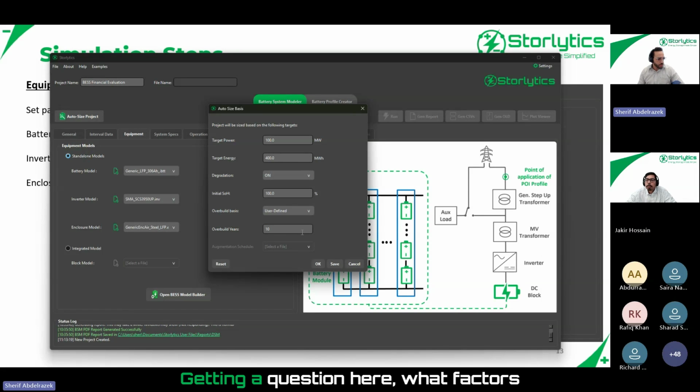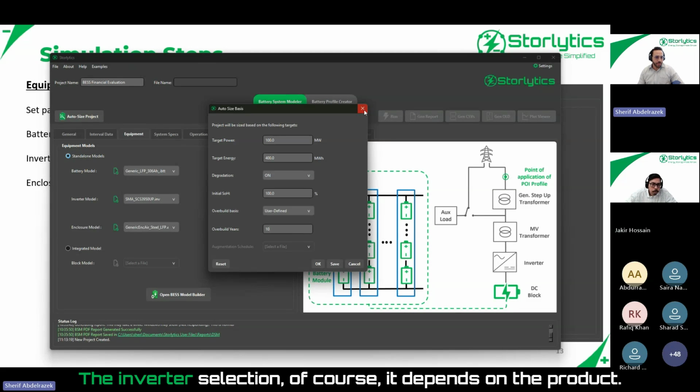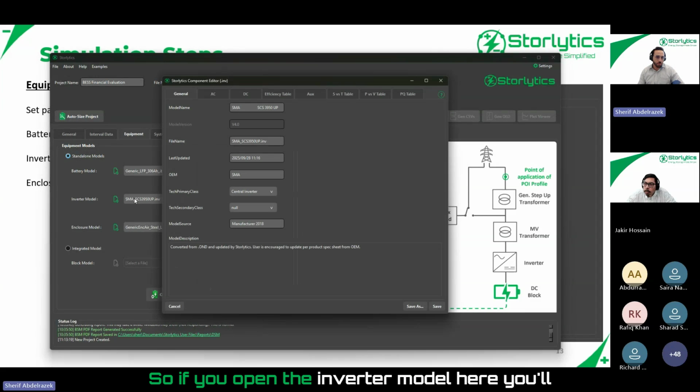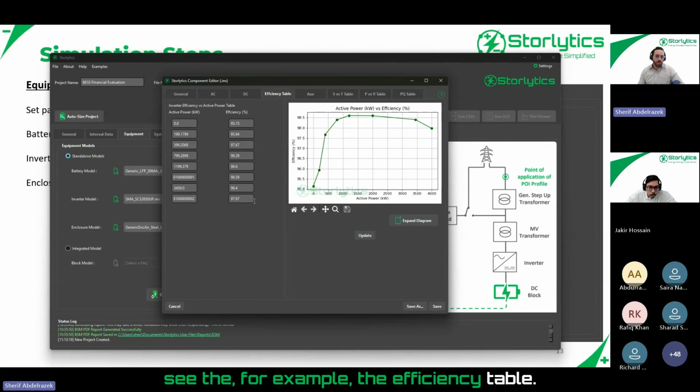Okay, getting a question here. What factors are within the inverter selection? Cost, RTE. The inverter selection, of course, depends on the product. So if you open the inverter model here, you'll see, for example, the efficiency table associated with this inverter. You can get this table from either the data sheet or the user manual of your inverter product.